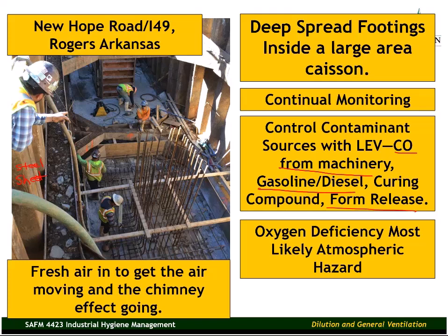Now, where I've had the bigger problems is when they're deep drilled shafts into the ground. 50, 60, 80 feet deep holes or pits straight down into the ground, and then you have to put workers down in there. That's where you're really going to have problems with oxygen deficiency. You absolutely have to have continual monitoring in that environment.